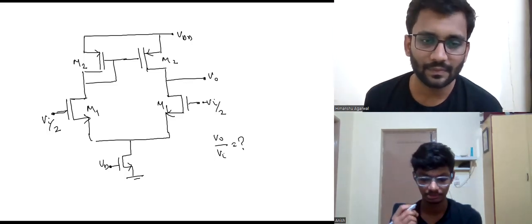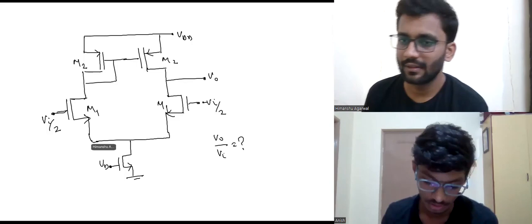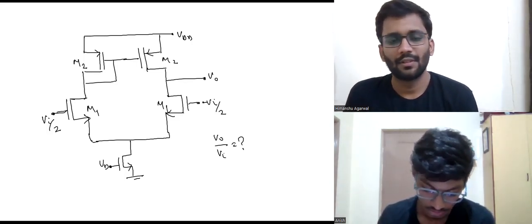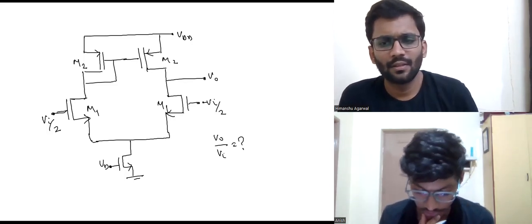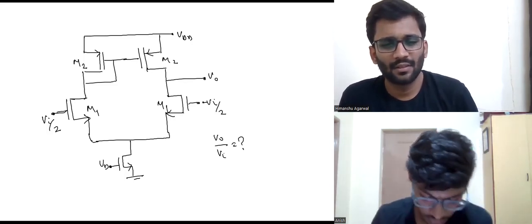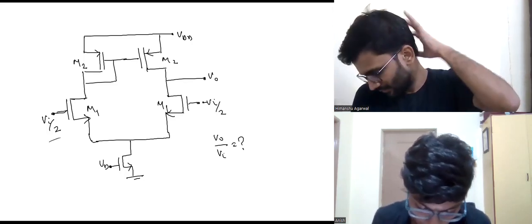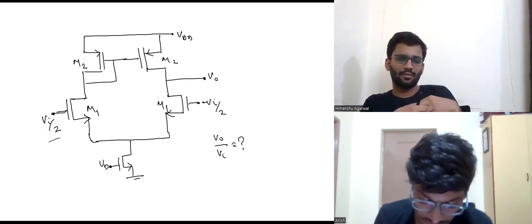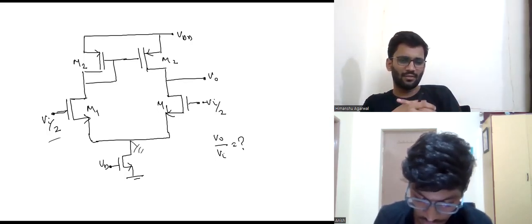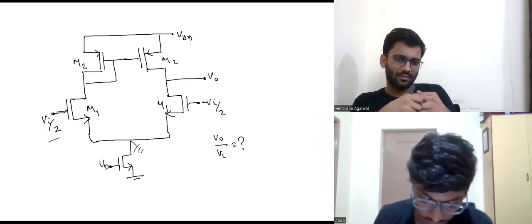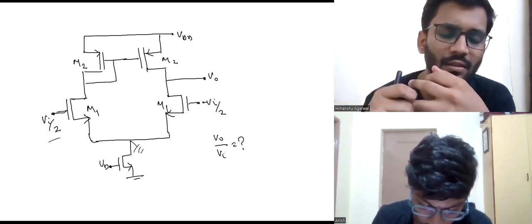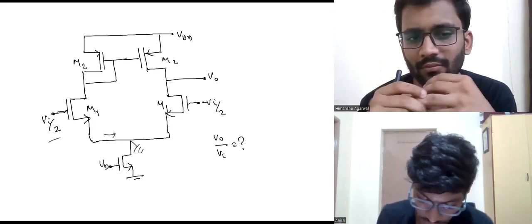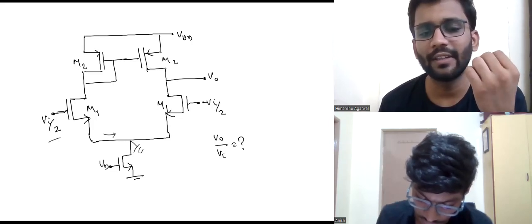So this is basically the differential amplifier when you are taking the single ended output. This is the standard circuit. So for the differential gain, we are already applying V in by 2 and minus V in by 2. So what happens is this becomes ground for this, right? Because no current flows through this end. Do you want me to prove it, or should we go ahead? Can you tell me intuitively why this potential goes to zero?